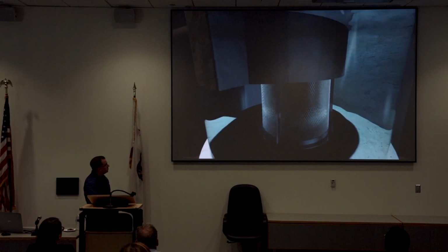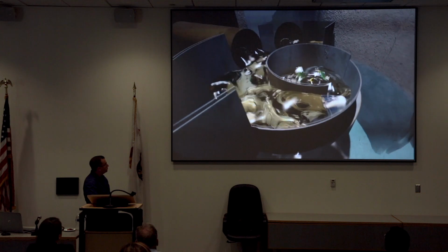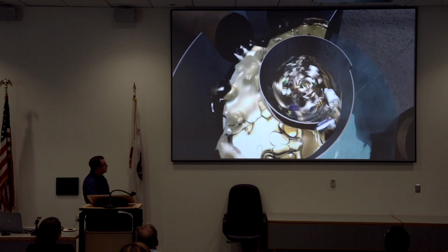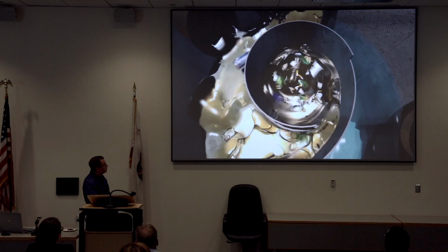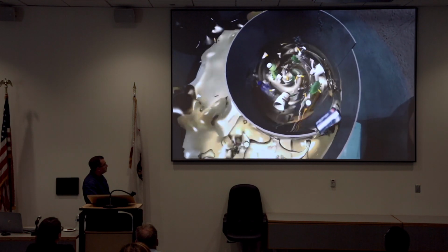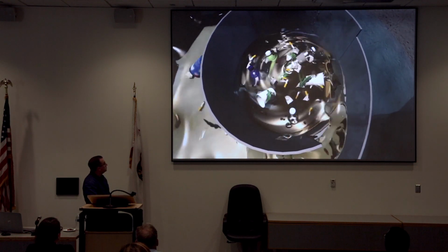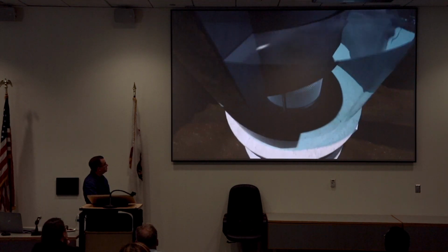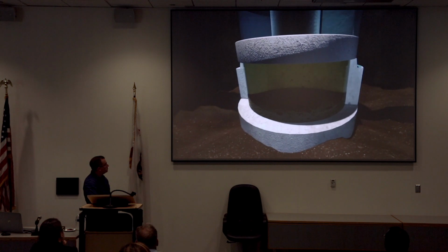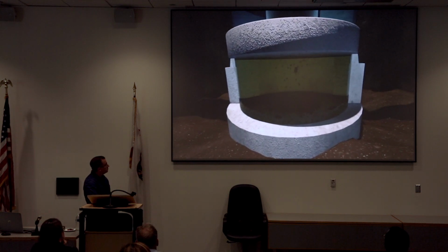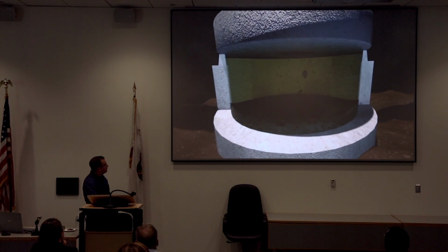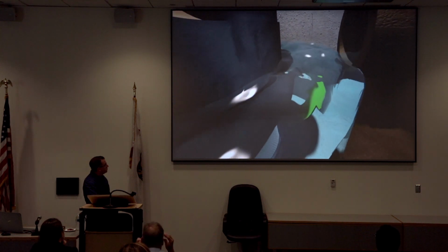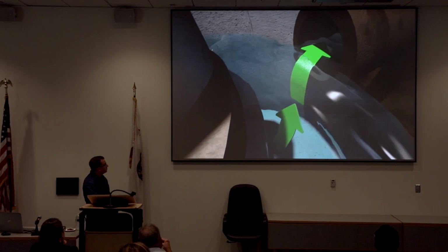The combination of swirl concentration and indirect screening forces floatables and solids to the center of the separation chamber. 100% of floatables and neutrally buoyant debris larger than the screen aperture are trapped in the chamber, and sediment settles into an isolated sump. Pollutants remain in these sections of the unit until they're removed during maintenance. Stormwater then moves under the hydrocarbon baffle, and the treated water exits the system.